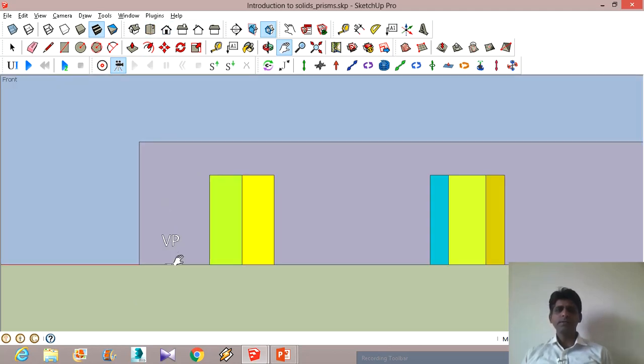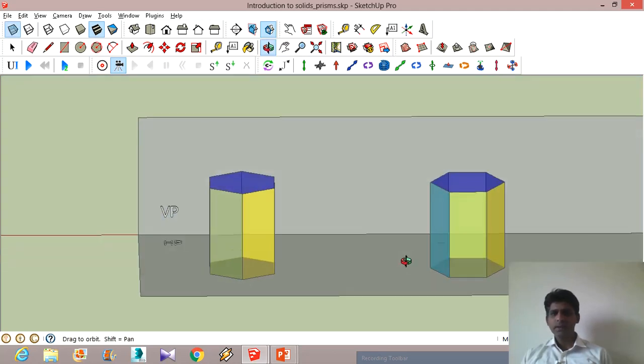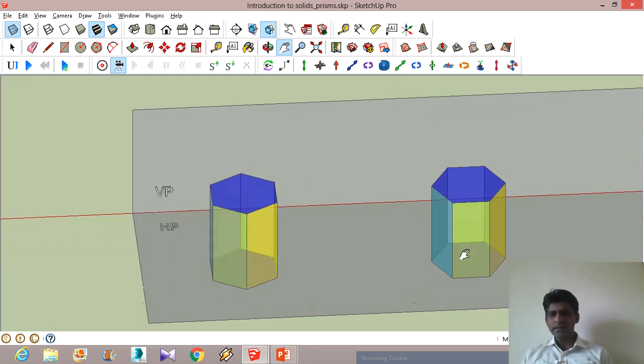See the front view of this. In this view, you can see only two faces, but in this view, we can see three faces. There is an axis here. In this particular view, the axis will also be visible. In this view, the axis is there, but in front of the axis, the edge is there. So this edge has to be represented by a continuous line. Whereas in this case, the axis will be represented by a chain line.